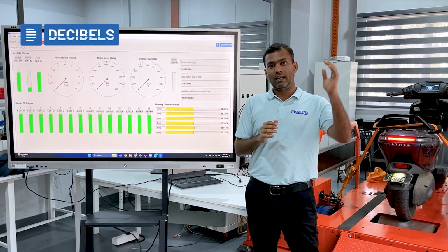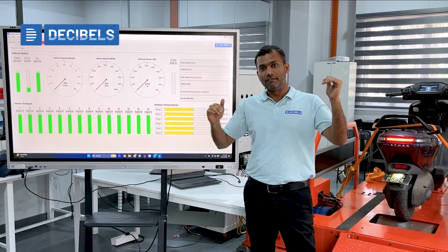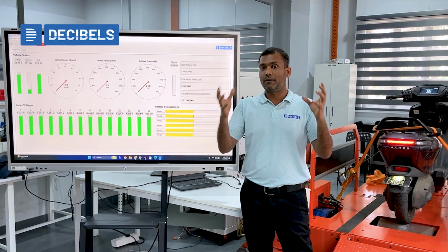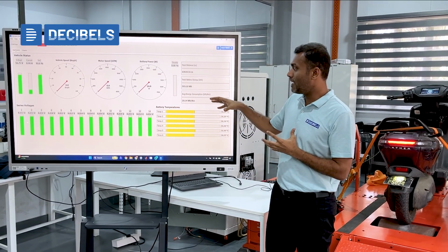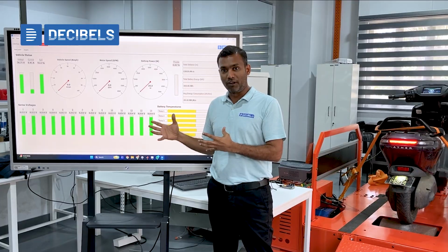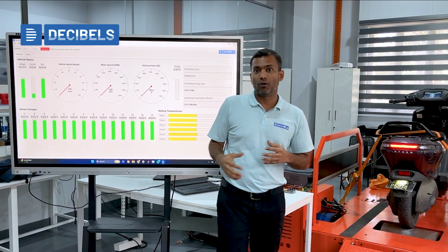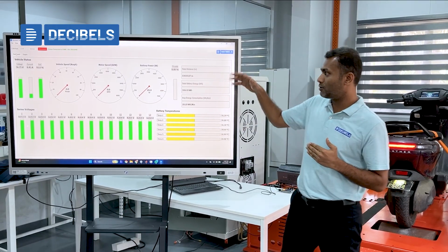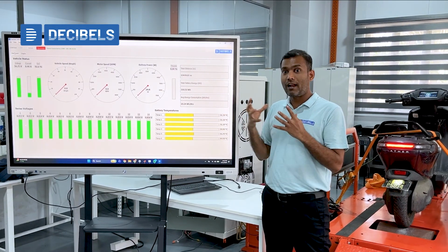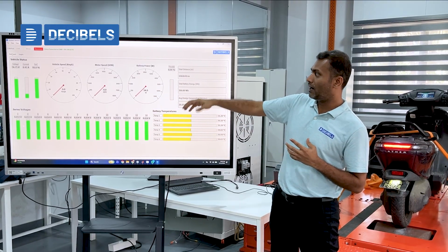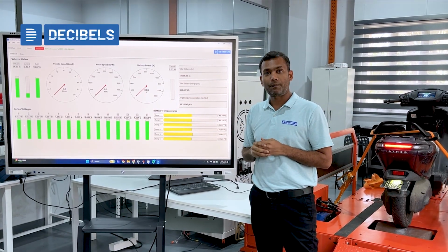Because as you understand, the voltage curve of the specifically used lithium-ion cells is different for a variety of chemistries. So you can understand that if the vehicle battery pack is designed very well, you don't see much voltage drop across the cells. And also, you want to make sure that at any given SOC, you don't have any sudden voltage jumps or SOC jumps. The setup gives you that kind of correlative learning opportunity to know the relationship between the pack current, the pack voltage and the cell voltages too.